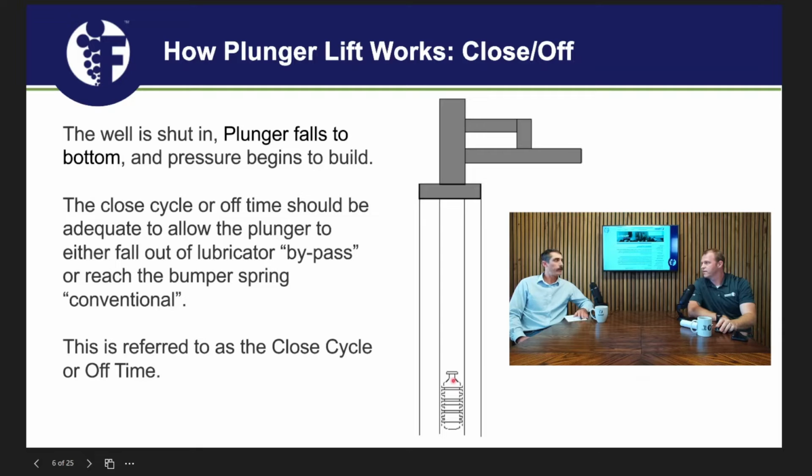Because it's just falling with gravity. Okay. And so then we're using that time to build energy, especially in older marginal wells. You know, it may take the plunger 30 minutes to get to bottom, but it may need to build that energy in the reservoir for an extended amount of time.